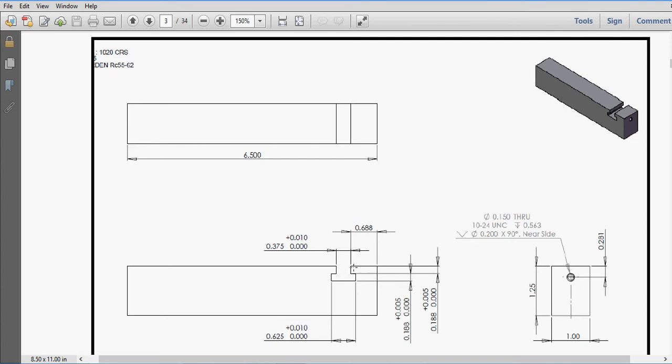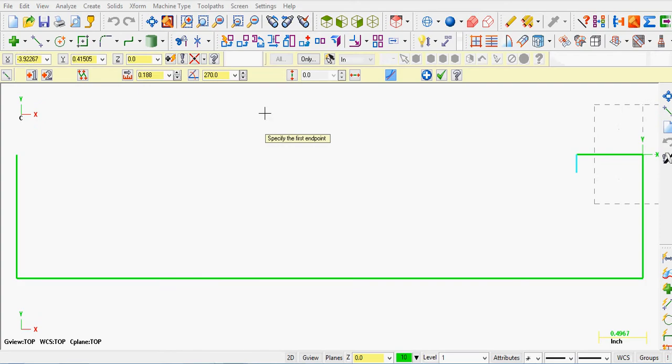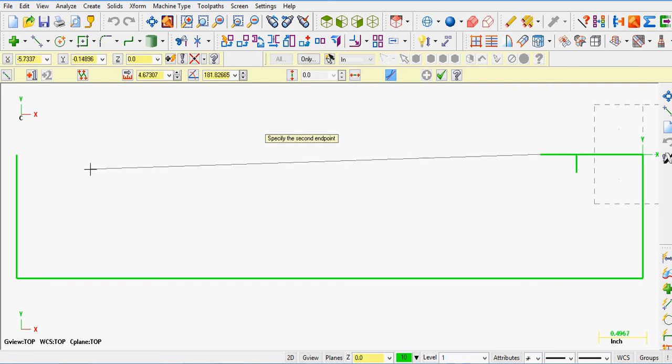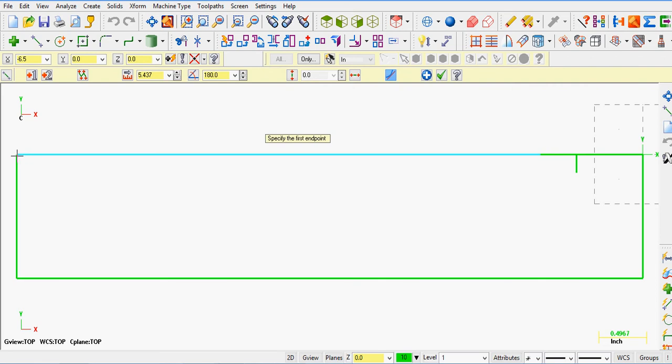So I'm going to create another horizontal line, starting here, going negative 0.375 in the x. Okay, so I'm in Create Line Endpoint. I'll select this as the first endpoint, and this time I'm just going to drag across horizontally and click. It's still blue, and what I'll do is now click in the length field and enter 0.375. Okay. Once again, I'm going to choose this as the endpoint for my next line, and I'll just come over and join it up with this endpoint. Okay. Still blue, not written in stone.